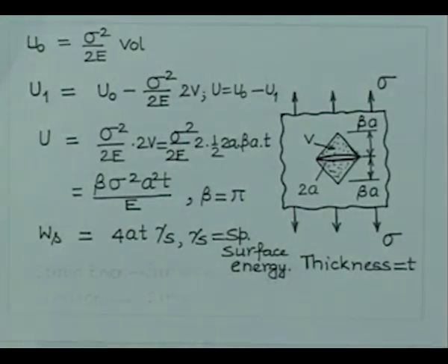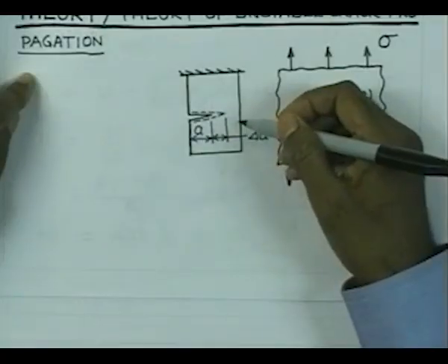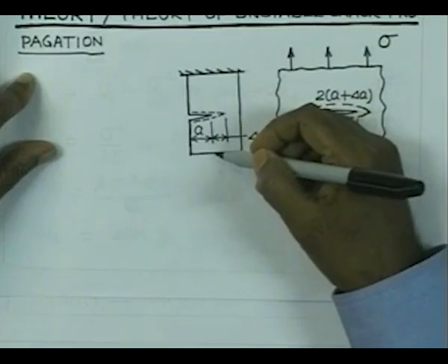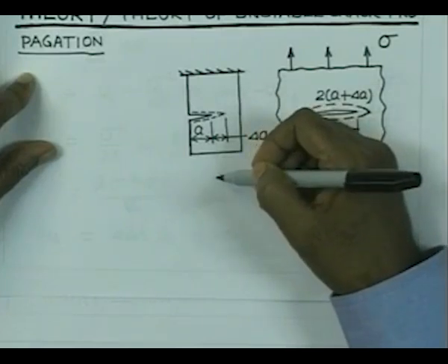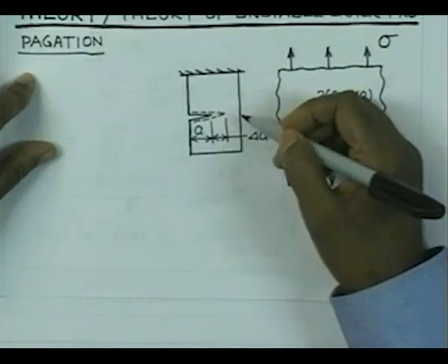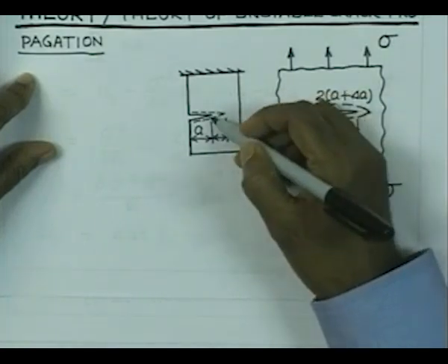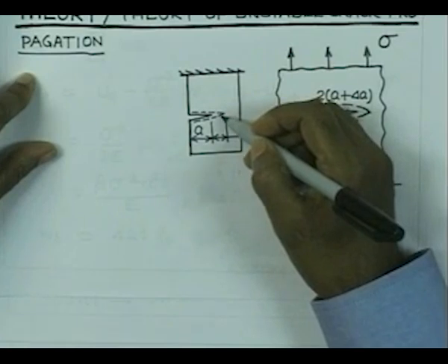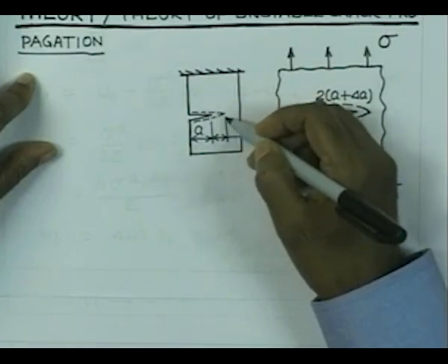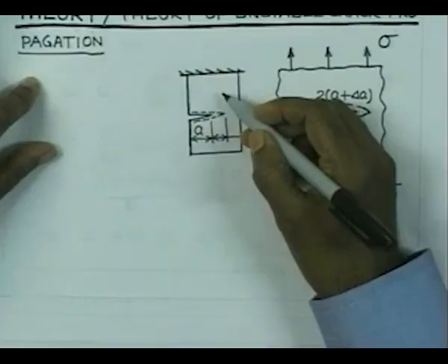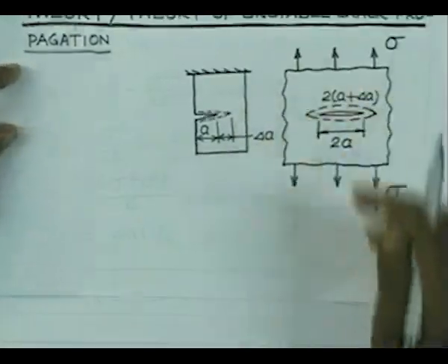Now, when we consider the loading of a component like this component, as you are deforming the component, you input strain energy in the body, and as soon as the crack extends, there is creation of new surfaces through the breaking of the bonds, and therefore, this strain energy is getting converted into the surface energy. So, while the crack propagation is taking place, you have really two forms of energy at play.